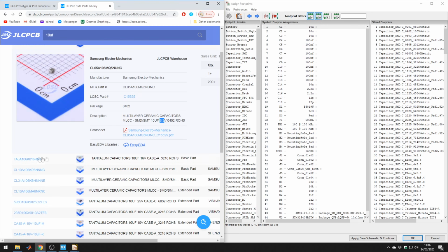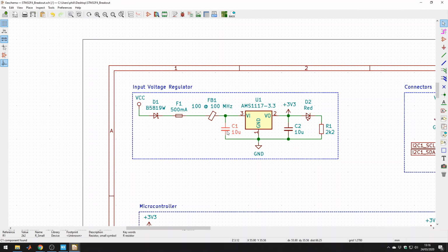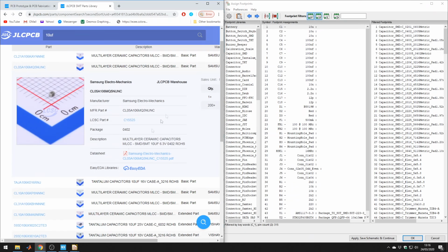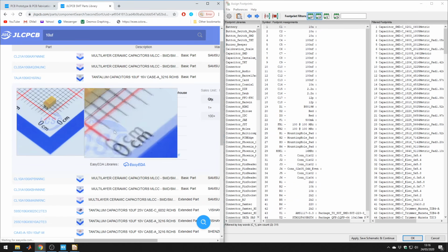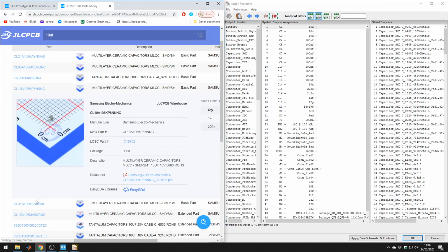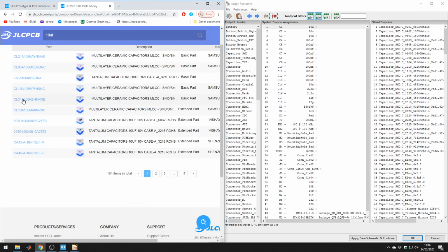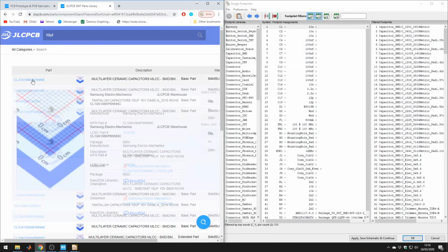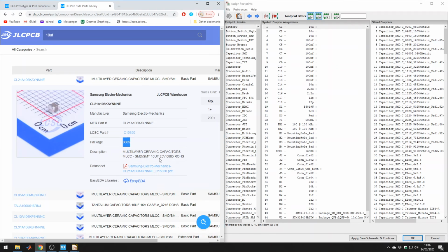See, there's a 6.3 volt rating, that isn't good, because especially C1, for example, will be at the input here, and who knows what voltage will be applied here. So if we put a 6.3 volt capacitor here, that might blow up. We also have tantalum. I wouldn't recommend that initially. So it looks like 0805 is the best choice. It's about 25 volt rated, let's choose that for the large input capacitor. So double click 0805 here, SMD 0805.